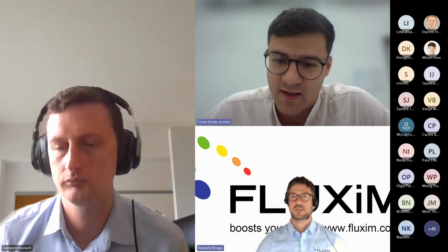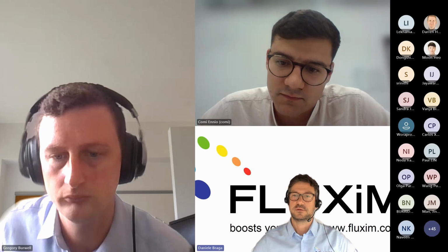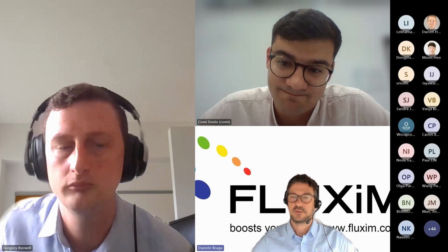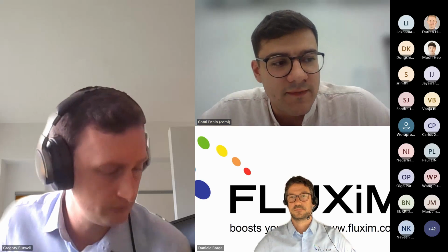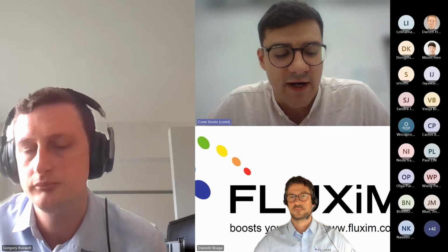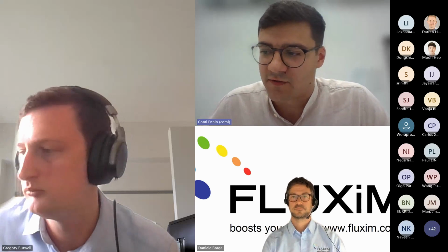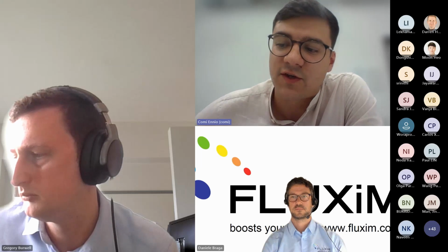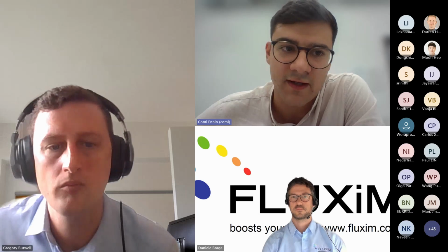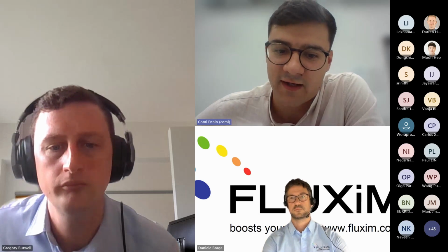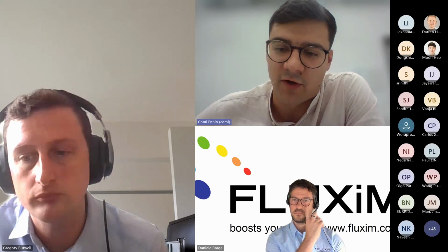There's another question for you, Ennio. Do you find that electroluminescence measurement causes a degradation to the device, particularly in the modules? In many devices that are not very emissive, sometimes we have to apply quite a high voltage, higher than the VOC, to get a good image. So this could cause some damage, but usually these measurements are done in a matter of a few seconds if there are not huge transients. So this shouldn't be very harmful for the devices.